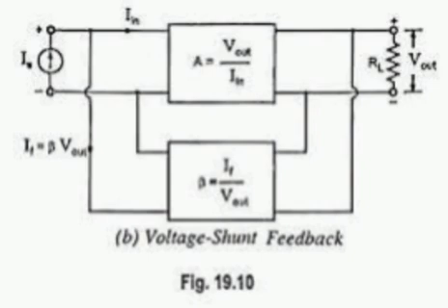Output impedance without load RS: Z equals numerator small rd plus capital RD, denominator mu plus 1, where capital RD is the drain resistance, RS is the source resistance, and R1 R2 is the parallel combination. If rd tends to infinity, then Z equals 1 by GM. Output impedance with load RS: Z0 equals numerator rd plus capital RD, denominator mu plus 1, parallel with RS. If rd tends to infinity, then Z0 equals 1 by GM parallel with RS.